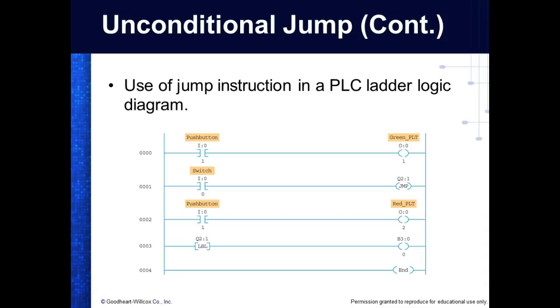So could it be like the pause on a percentage? Could be a pause on a timer, or we jump over the timer. We could actually use it on a counter, if I wanted to jump over a counter, you understand that? Or like I wanted to turn on the blower if a pressure switch got up to a certain level, but I wanna jump over it if it's not at a certain level.